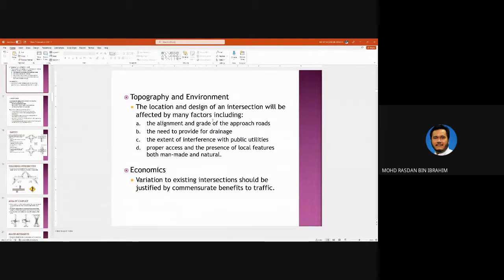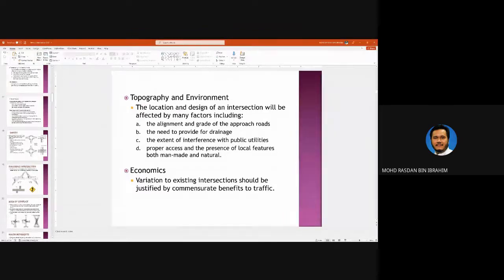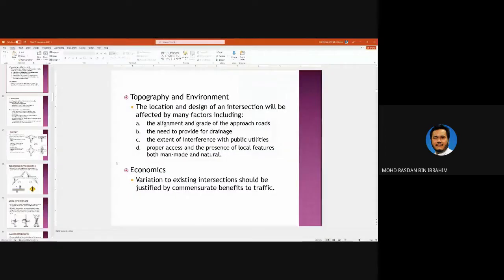And the ending of your alignment will be very close to another, existing bridge on the road. Is it road A or road B? Road B, I think. So you can think about it: is it allowable to have a junction over there or not? You need to consider the sight distance. But it's okay, this is just for you to check. I'm not going to give or deduct points because of the junction.